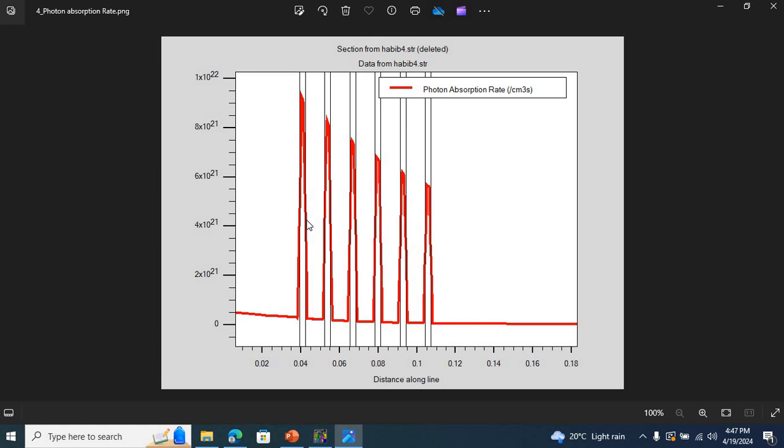And that is because the band gap of gallium nitride is 3.4 electron volts. The input light is the solar spectrum, right? Now the solar spectrum runs from UV to infrared, and for gallium nitride only the UV part of the light is going to be absorbed, but not the rest of the light.